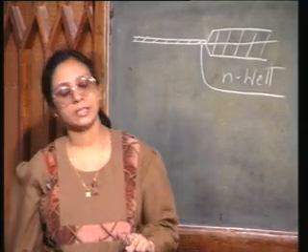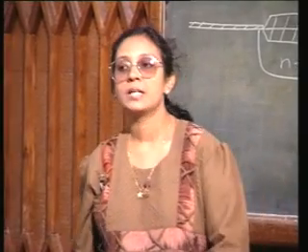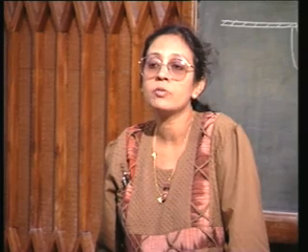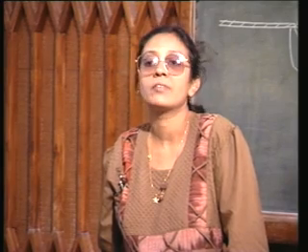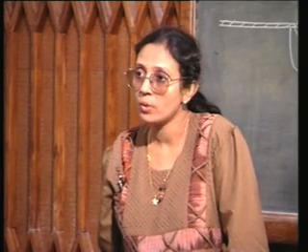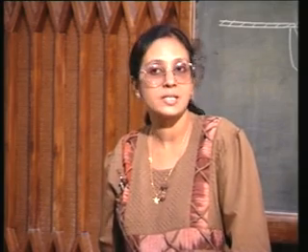The whole point is this: as we are reducing the device dimensions, it becomes more and more critical if we have a lot of mask alignment to do. The smaller the device dimensions are, the more difficult it is to align. So, we always want to go for self-aligned technology, where one region is automatically aligned to the other. So, this is what we are achieving here.